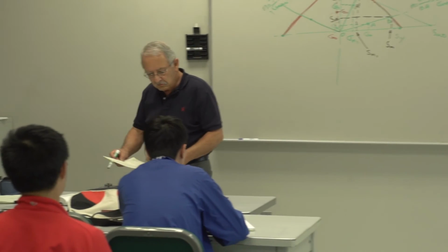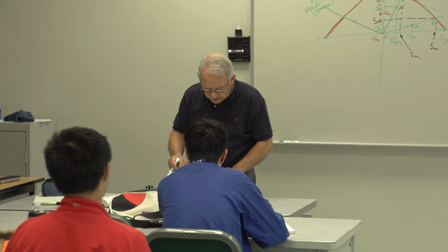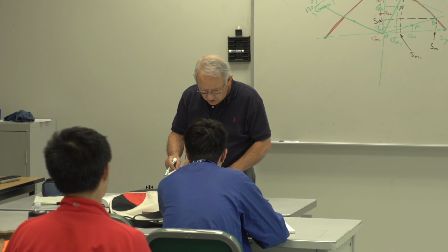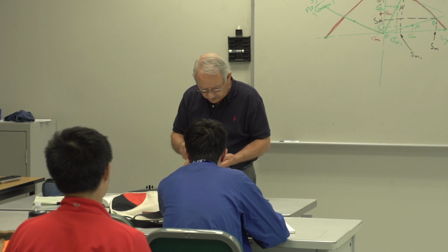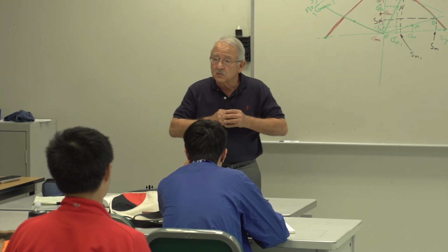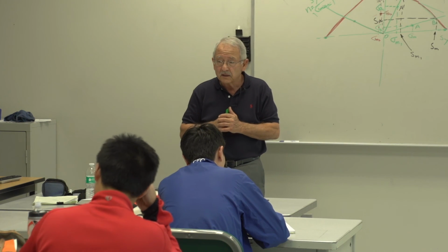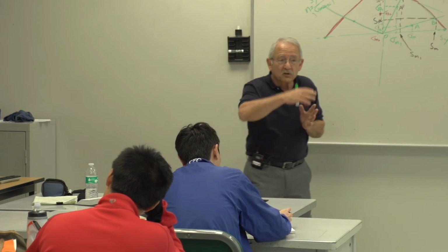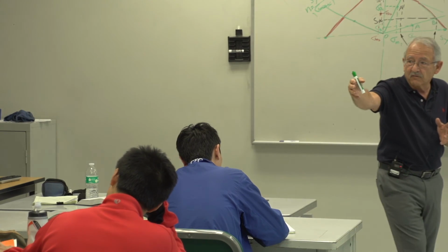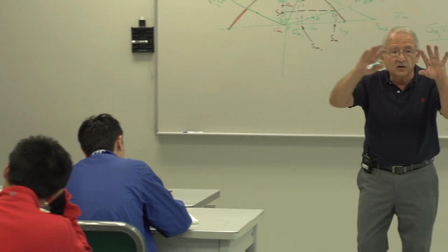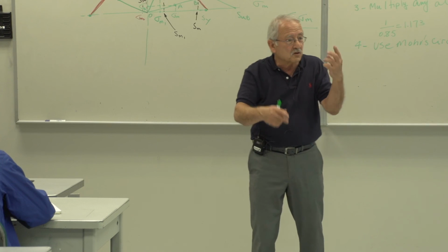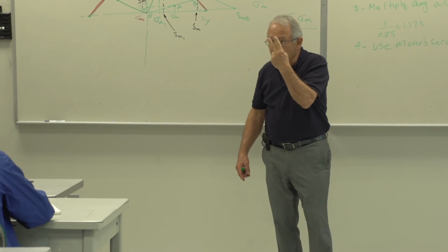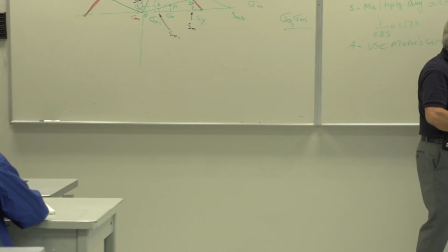This is essentially exactly the same type of analysis that we just did with the example problem that I had, except at first you had to use whatever you learned from von Mises to convert a complicated state of stress into just two stresses, sigma A prime and sigma M prime.